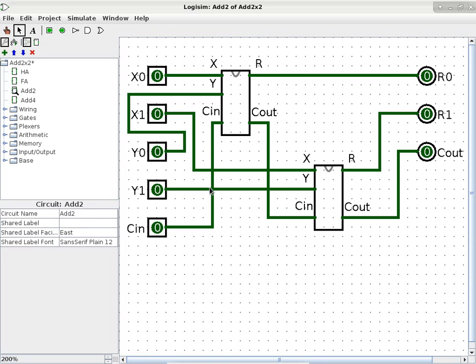But at least if you say, okay, I understand the difference between the designs: if you have ripple carry, the delay is proportional to the number of bits, but when you do it the other way, it is a constant delay. Okay, you only have 3 gate propagation time. Then the interviewer knows, okay, you know practical terms. You know what is practical in industry, and not just textbook cases like that.